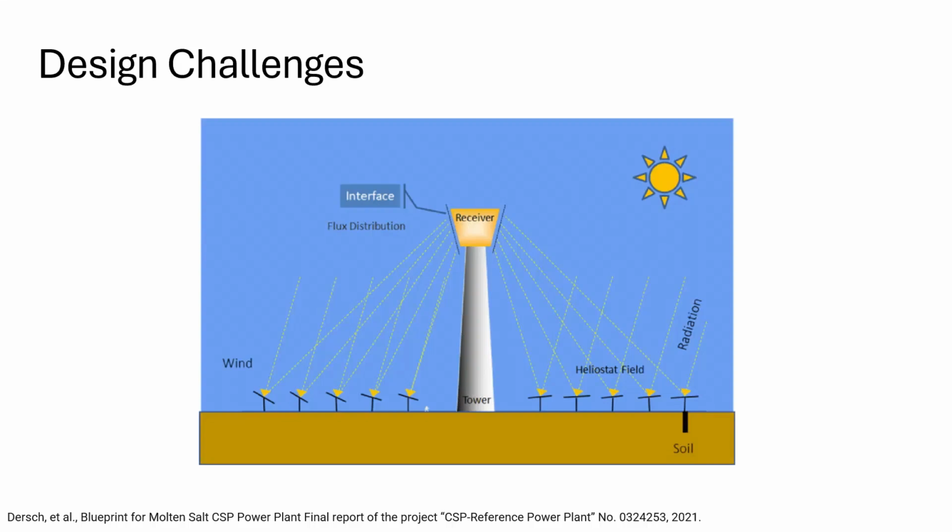Now, there are a lot of interesting problems and challenges with this design. For example, the angular displacement of the heliostat has to be really perfect to be able to reflect the sunlight to the receiver and focus this properly. So any small angular deviations can actually reduce the performance of the energy harvesting effort. And to that end, how does one know exactly what the angle should be? So there must be some type of sensors and instrumentation at the receiver end that can tell the heliostat whether or not its angles are correct. And imagine you have many of these heliostats. How would you do that properly? You can collectively orient these, let's say, mirrors to focus the sunlight in the most optimal manner.